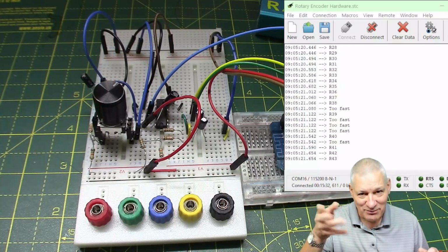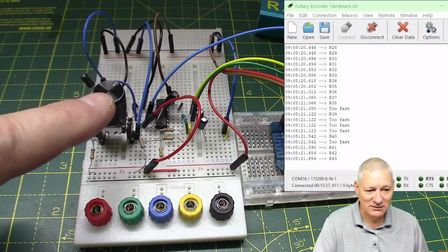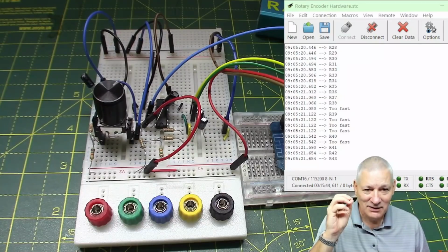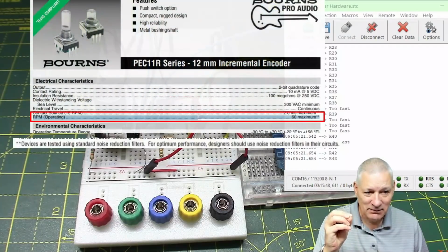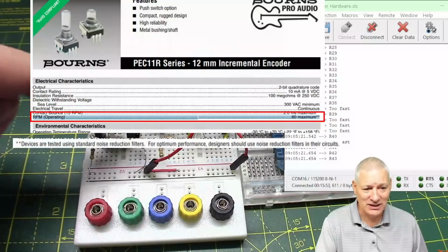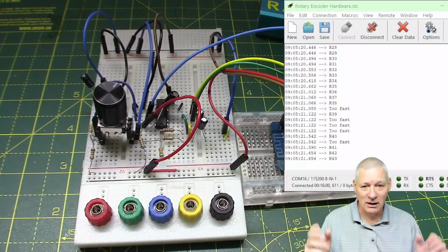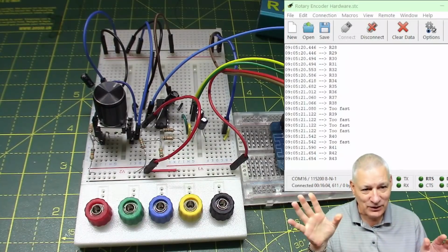Okay, I've put that in the code now because when I looked at the data sheet for this particular rotary encoder, and most mechanical rotary encoders are the same, the maximum RPM is 60 RPM. Now that doesn't mean you can whiz this round at a rate of knots until you get to one click from the 360 degrees and then wait a bit and then click that final one and go, oh, I only turned it at 60 RPM. No, this is more like an average speed camera you find on the roads.